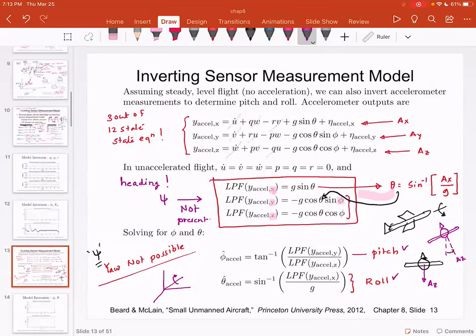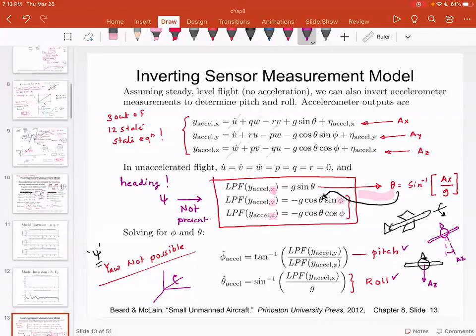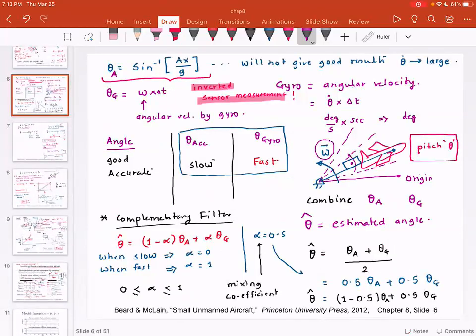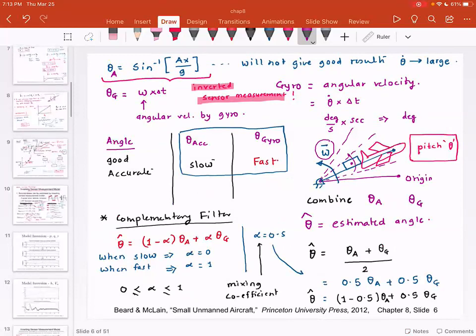This will need a little bit more discussion, and I plan on doing this again a little bit in the next class. But what I want you to understand is, if you have a three-dimensional accelerometer, to be honest with you, to find roll and pitch you just need two accelerometers. So with the system that we started with, with two accelerometers, we can find out roll and pitch, no problem.